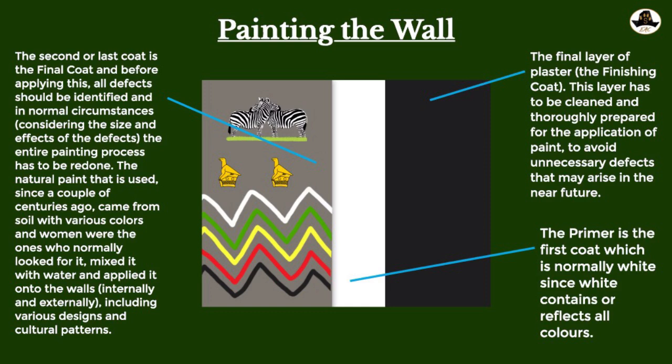And then what else is left? We have coats. Yeah, so we have the final coat of the plaster, and then we have basically the final coat of the mud. I'm saying plaster just to use some terminology in the construction, but it's basically just mud. Yes, soil and water, and then you mix. But if you want to enhance the strength of the bonding nature of that material, of the earth material or the mud, you then add some cement. Cement helps with the bonding element of the mortar or of the earth material. That's why you find that in mortar and concrete, you have the use of cement. So it's a bonding agent.